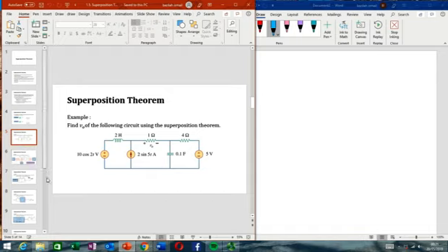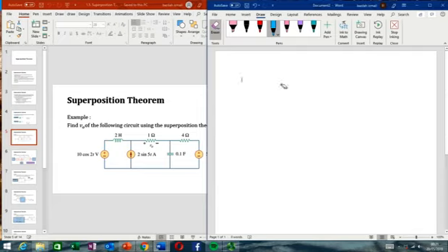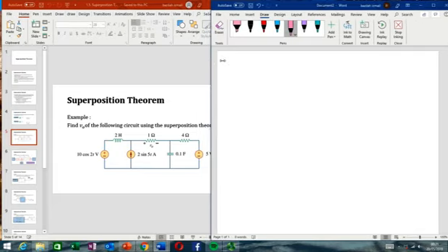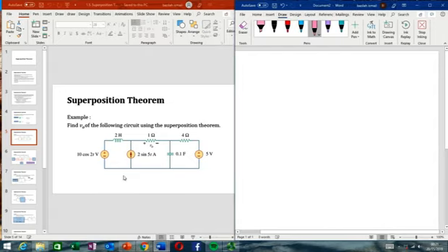Okay, let us go through this example, the only one example. For this case, we have a circuit that consists of 3 sources, where we have 2 sources in AC and another one is a DC source. For the AC sources, one is a current source and the other is a voltage source. If you look at the frequencies, the 2 sources are different: for the voltage source the omega is equal to 2, and for the current source the omega is equal to 5. So this system works at 2 different frequencies, and the values of XL and XC will be different in this case.